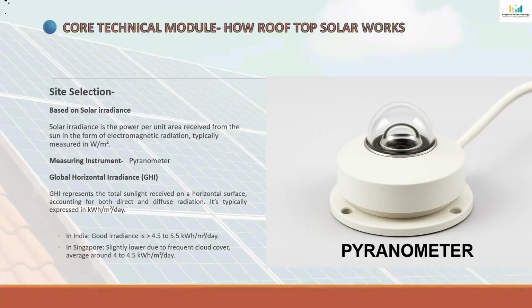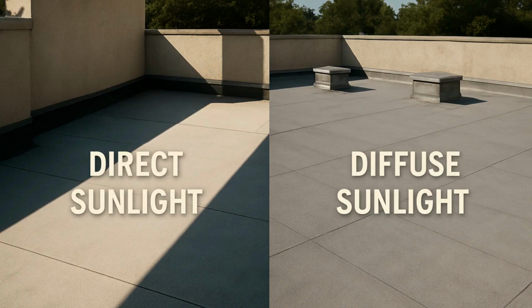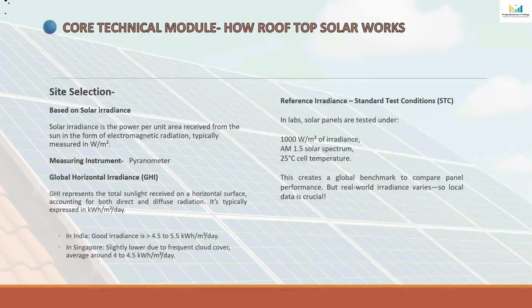It measures all the sunlight falling on a flat surface, including both direct radiation and diffuse radiation. Direct radiation means sunlight that comes in a straight line from the sun, and diffuse radiation means sunlight scattered by clouds and particles in the atmosphere. The term GHI stands for global horizontal irradiance. It is the total amount of solar energy received per square meter on a horizontal surface over a specific period, usually measured per day. So the unit we use here is kilowatt hour per square meter per day.